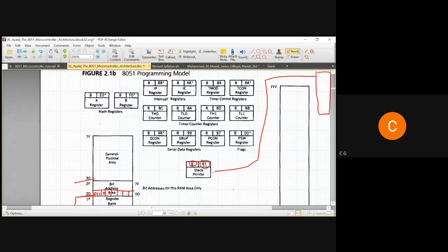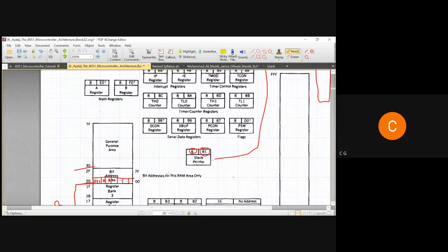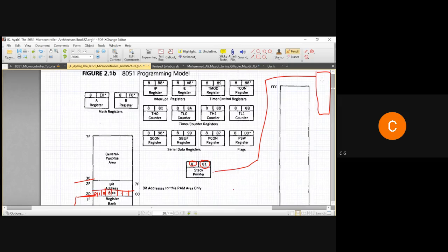Like this, and from here the data will come into the stack, or it is assumed that it is storing the address of this particular memory location. So what happens whenever the CPU is initializing any program? In the normal case, whenever you start the machine, the CPU will initialize the stack pointer. Stack pointer will jump to the address 000 of the external memory location, right? So it will read the instruction in this, and then it will store it over here.